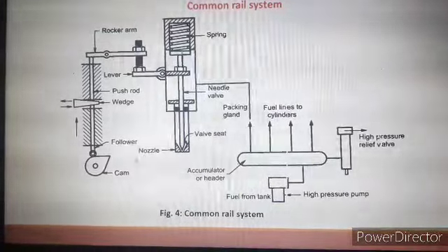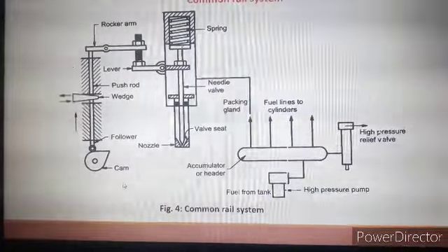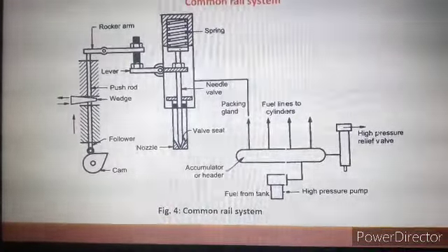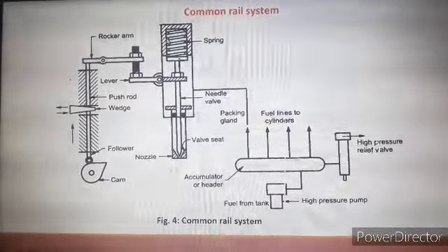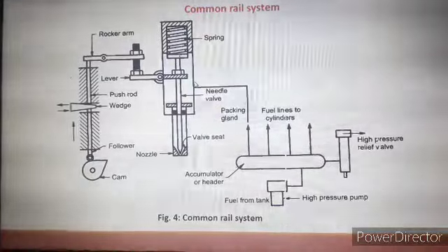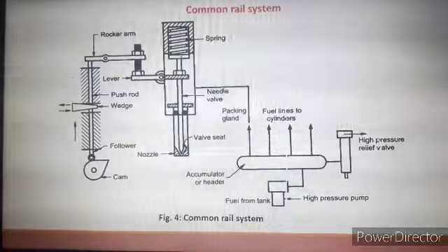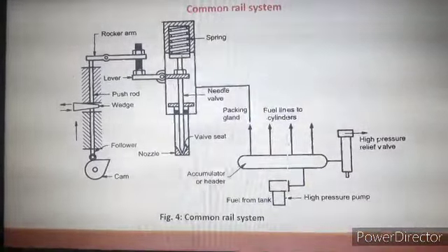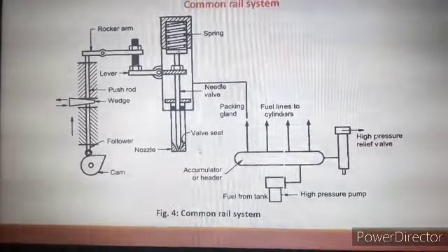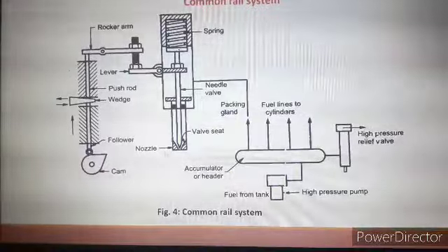As per the operation of these strokes, our valves operate, and that operation of the valve is carried out by this cam and follower. So this is the mechanism used for operation of the valve, and indirectly as per the operation of the valve our fuel system operates, because we have to take fuel inside the cylinder at the end of compression or before the start of the power stroke. Accordingly, this cam and follower mechanism is used to supply the fuel to the respective cylinder through the respective nozzle. This is the same nozzle or fuel injector.